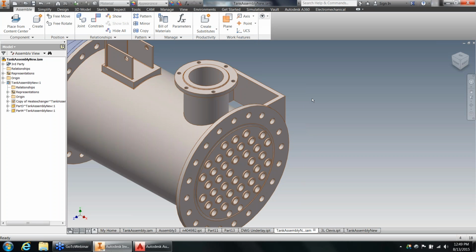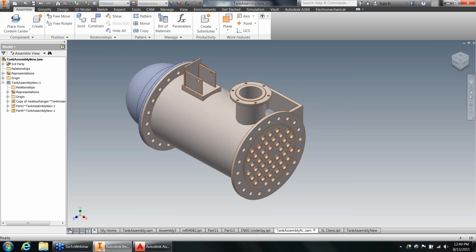And yes, the copy design functions as well in here. The big thing there is just making sure you work with the copy design interface to specify what objects are copied inside of that space. So, new SolidWorks design, new entries within it. And there are some plugins that work with the Vault. I don't believe Vault Basic can handle the full functionality as far as being able to truly capture the full breadth of SolidWorks and Pro Engineer file relationships. But the higher level of vaults have plugins that can be added relatively easily inside that space.